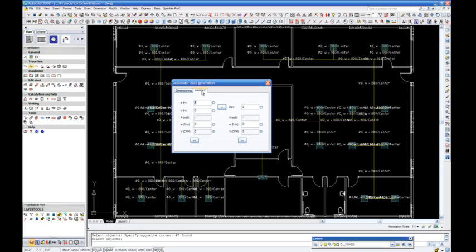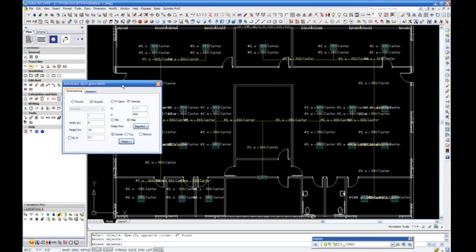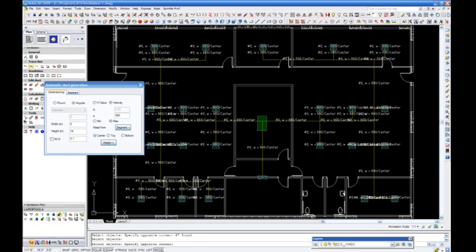The Automatic Duct Generator window has a tab to the right which is labeled Assistant. This is nothing more than a duct calculator. Now all the information is displayed in yellow as the round duct system. We will now select the ducts to be converted from round to rectangular. We will assign our rectangular duct height.